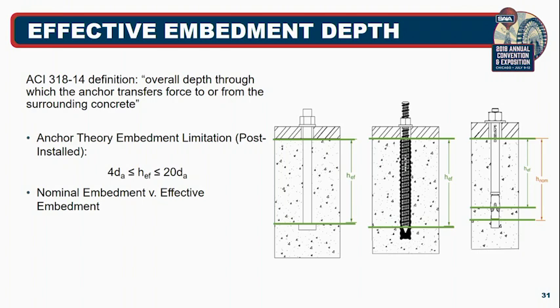So it's typically to the power of about 1.5 until you get steel failure occurring. Something important to take into account with this one as well is that there is a nominal embedment depth and an effective embedment depth when it comes to mechanical anchor systems. The nominal embedment depth is the embedment depth when you first place an anchor, say, for example, a torque-controlled anchor. The effective embedment depth is once you've torqued up that anchor, so like for example with this